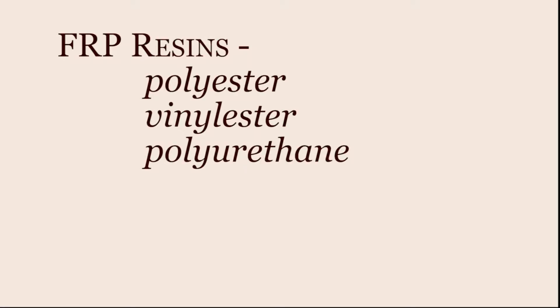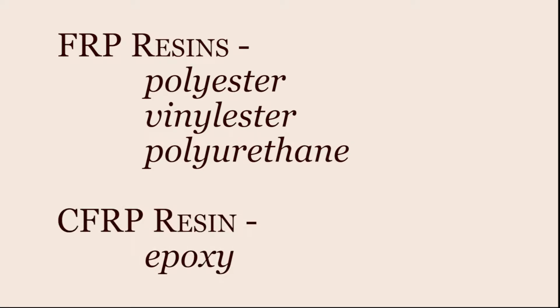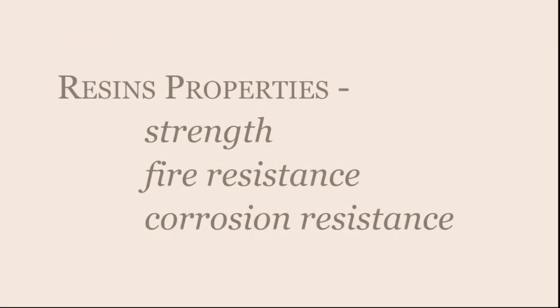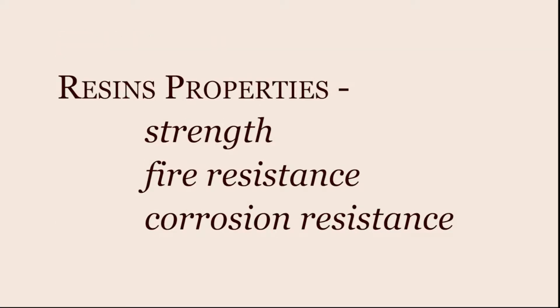Resins. FRP resins are typically polyester, vinyl ester, or polyurethane. CFRP composites use much stronger epoxy resin. Each of these resins exhibits variation in properties such as strength, fire resistance, and corrosion resistance. Molded FRP.